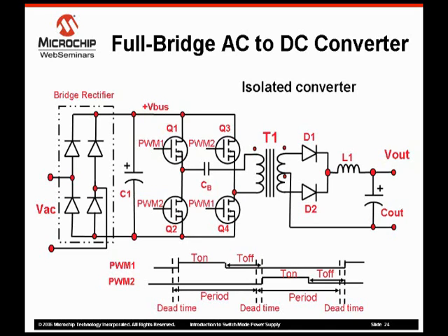The flux hysteresis loop operates in quadrants 1 and 3, so the core utilization is high, allowing the use of a smaller core. The input to output voltage transfer function is proportional to the input voltage, duty cycle, and the transformer turns ratio.